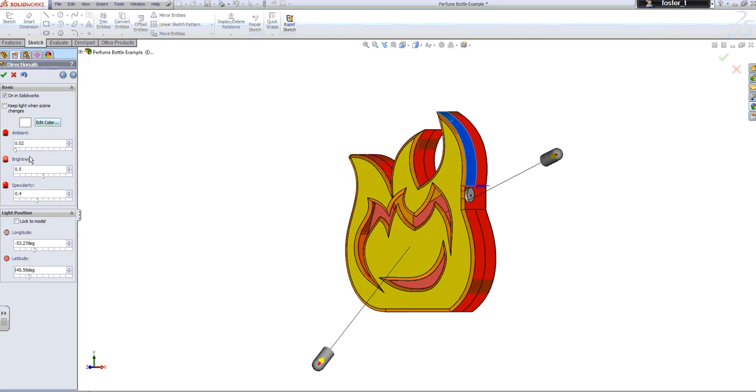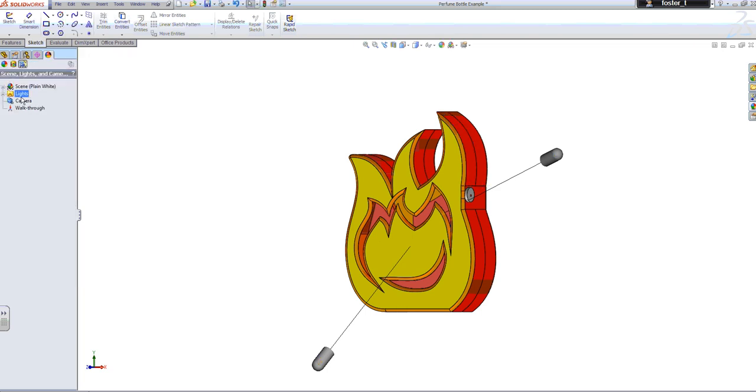You can also change the type of lighting, the brightness, or the type of colouring of the light that you want to put on that from this option over here. This is in Lights, Edit Lights. You can also add another light if you want to, so you could add a directional or a spotlight in one particular point. In here, look, we can check on what we've got so far.